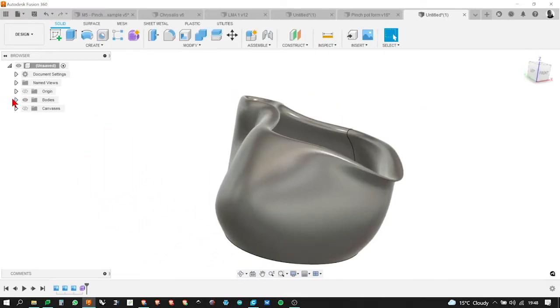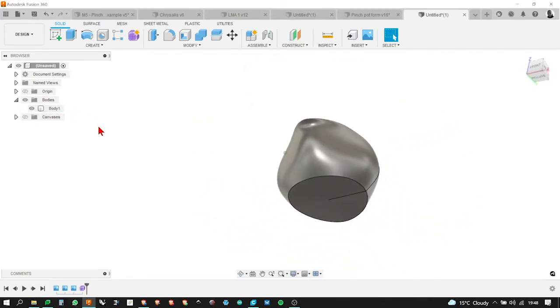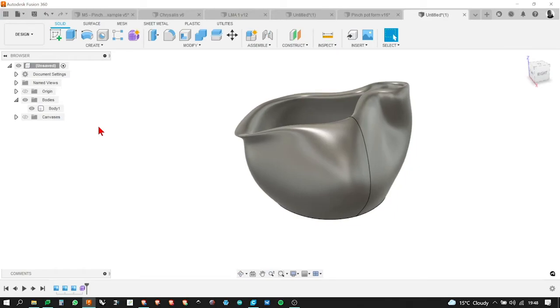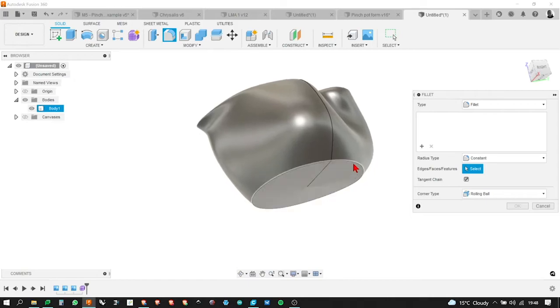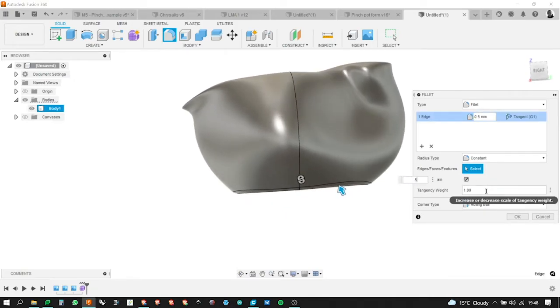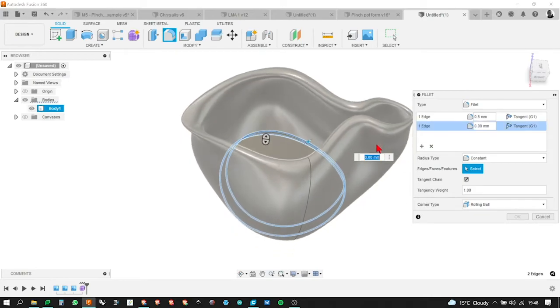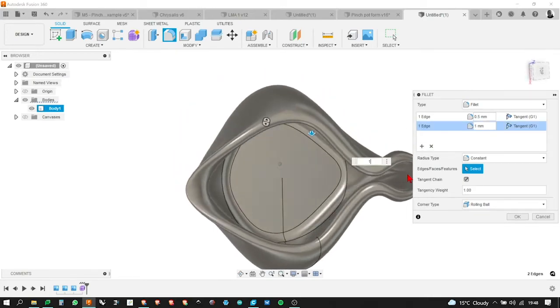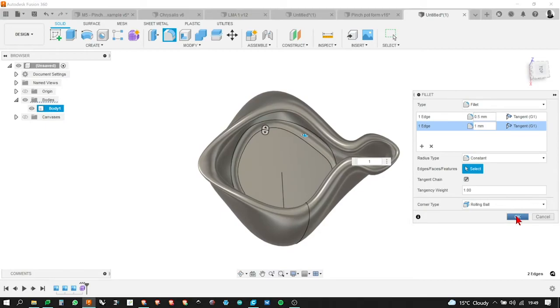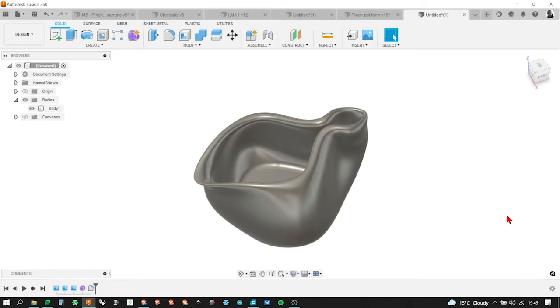And it's come in as a one-off solid body. And that's pretty much it. But now I could also fillet it. If I wanted to put just a slight radius on this edge, I could do so, just to smooth that bit off, but it's still got that nice flat bottom. And I could also put perhaps a fillet on the inside as well, maybe a slightly bigger one, just to smooth that internal surface off as well.